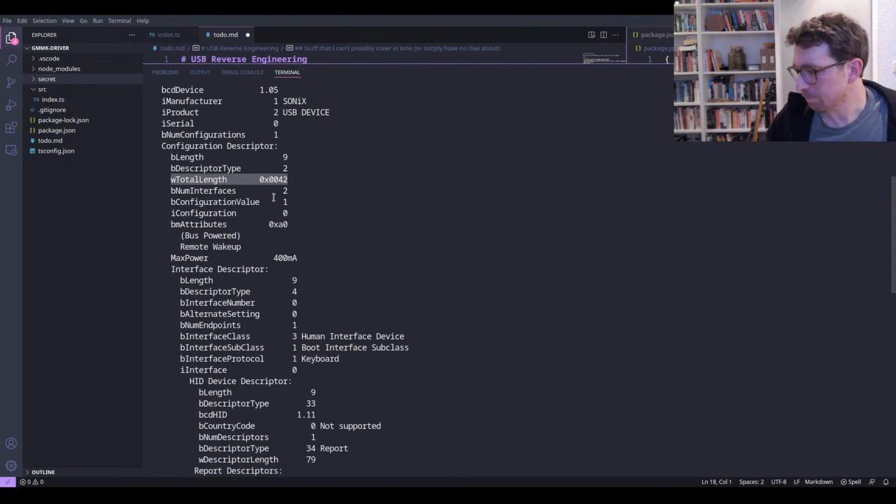And there are different kinds of devices in USB. They actually standardize a whole bunch of fixed devices, like keyboards, mice, cameras, microphones, payment systems, point of sale kind of systems, also MIDI devices and things like that. In each of those, they have their own special information that comes along with the standard information. So they vary in size, and that's why you get things like this total length. This is going to tell us how many bytes there are in total, describing all of this stuff.